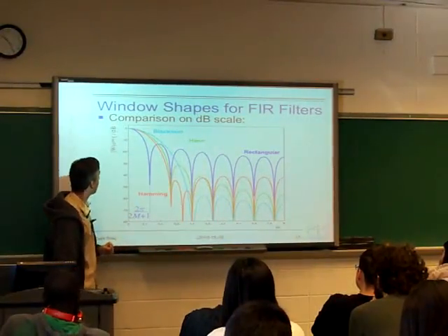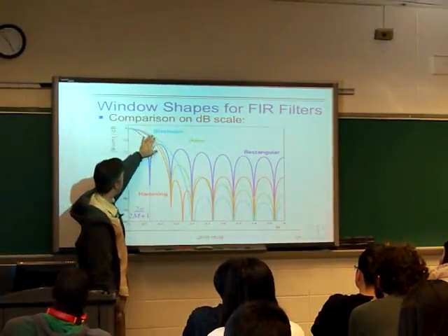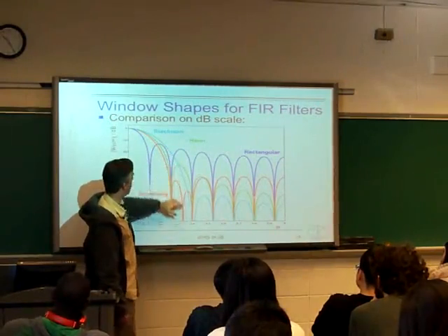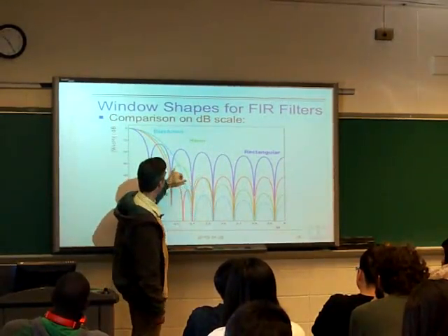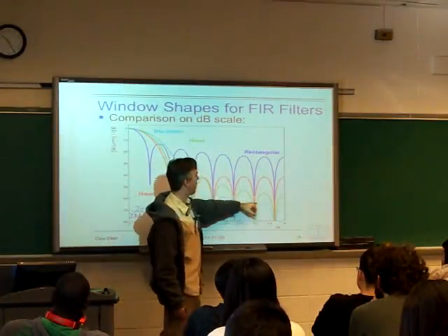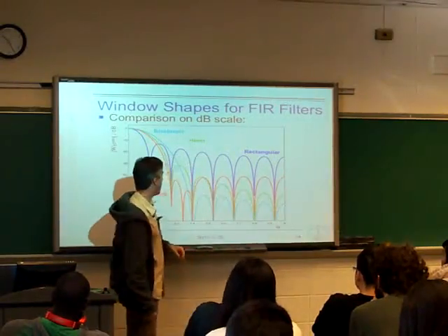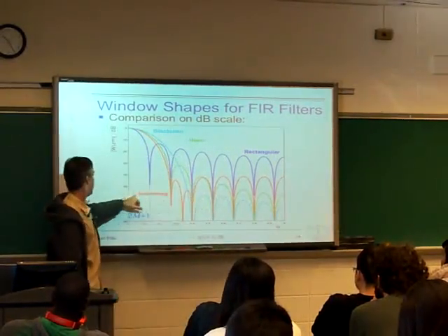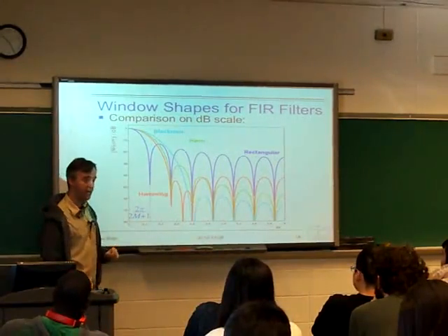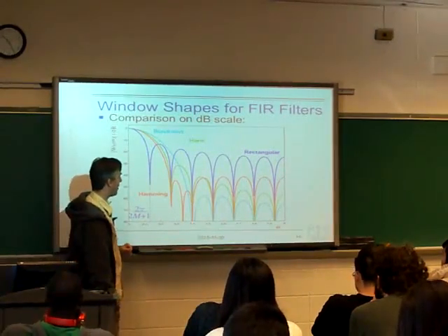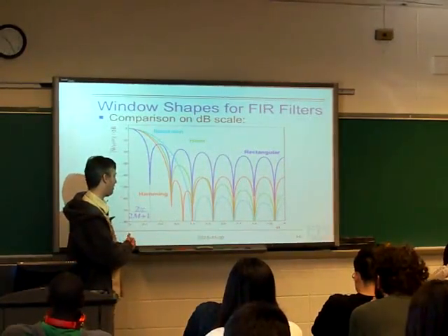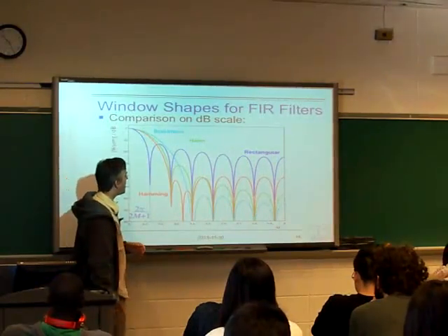better choice. And then finally, the Blackman window is even broader in its main lobe, but it's got similar performance to the Hann of having these low side lobes which die away with frequency. But now the largest one is almost minus 60 dB, which is a nice rejection. And in a sense, it's like, well, which is worse?